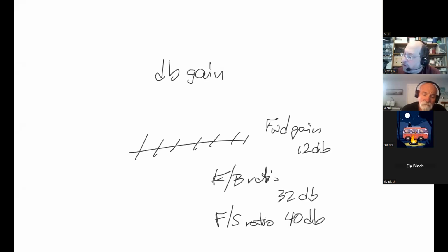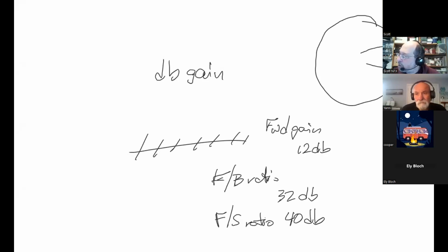This means that somebody used a plot and they actually took a circle and they found that if this is the 0 dB line, the pattern would look like this. And it would max out at 12 dB. And in the back direction, it would look like this. It would have a little bit of power going backwards and more power going forward. And then you could also from this figure out your 3 dB beam width, as it's called.